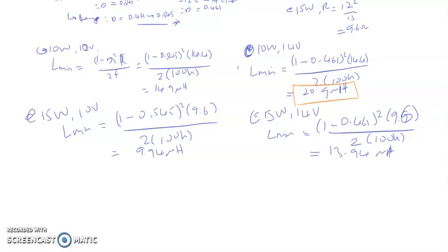If you choose the smaller one, and that condition happens, the inductance will not be sufficient. But if you choose this one, it will comply with all other conditions. This means the biggest value is preferable to ensure that at all conditions the circuit will operate at CCM.